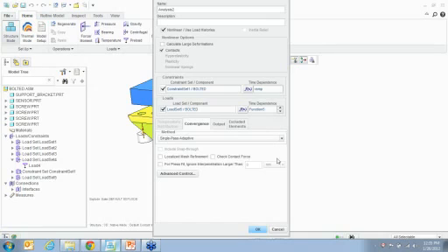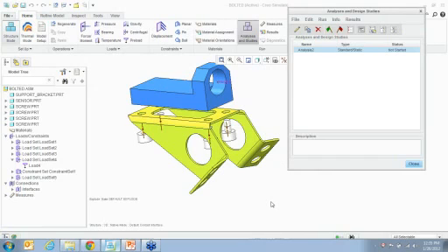So what this does is that for the first 1 second, only the first bolt load is applied. After that's applied with its preload, it's fixed in place, then the second one's applied, then the third one, then the fourth, and then finally the main load.